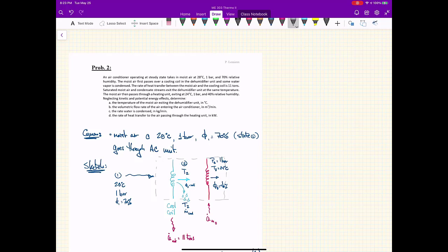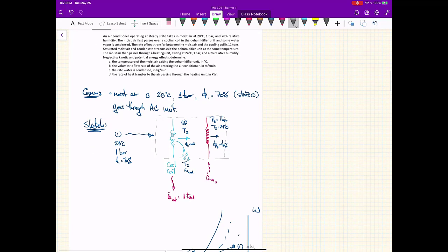And of course, what's going to come out of that process, once we start squeezing the water out of it, is that what we're left with is much colder air, but that's saturated with 100% humidity. So to get ourselves away from that uncomfortable saturated air state, we're going to reheat it to our set point temperature that we want. So dump heat into that air, dry heat into that air, keeping the humidity ratio constant, keeping the total pressure constant.